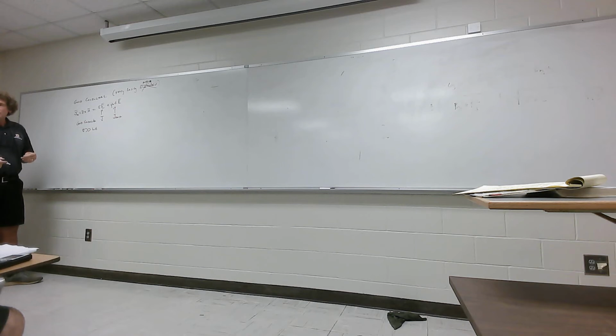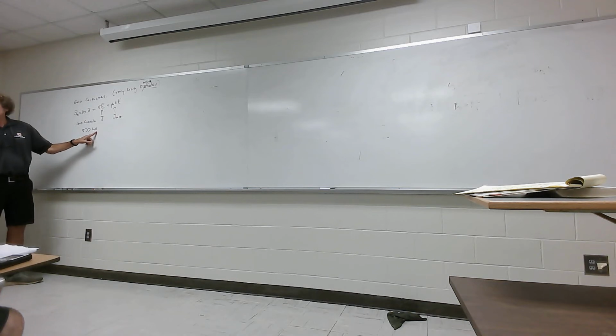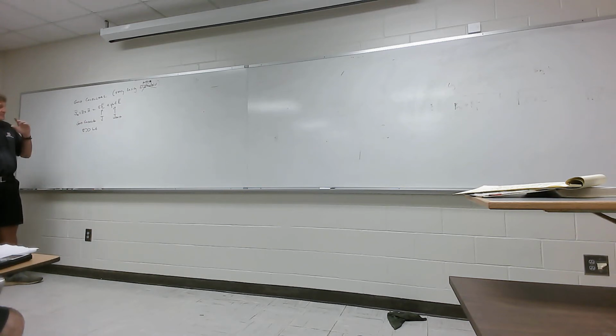So that's how come if you take a look at things like copper, which has a conductivity of 5.8 times 10 to the 7th Siemens per meter, and compare that to the value of omega epsilon for any frequency of interest, this is insignificant, it's like 5, 6 orders of magnitude less, you follow me? So that's the definition of a good conductor.